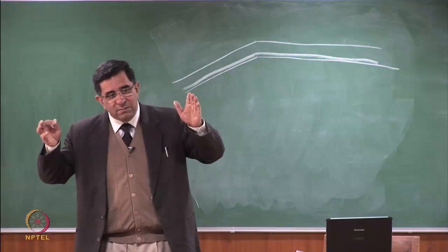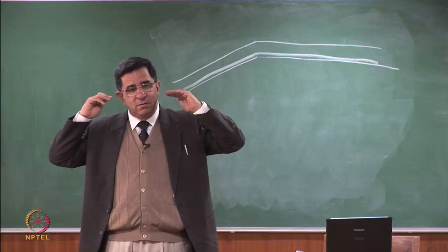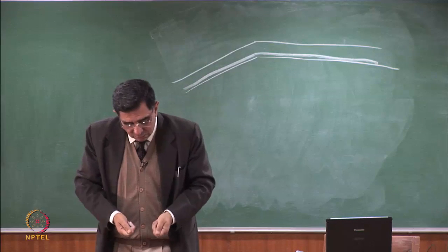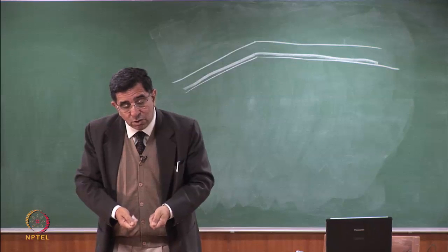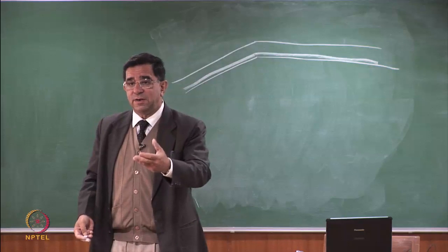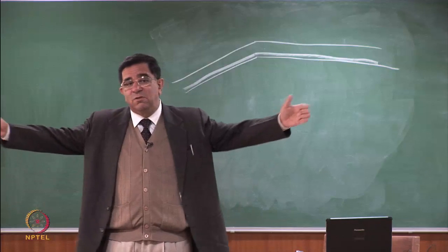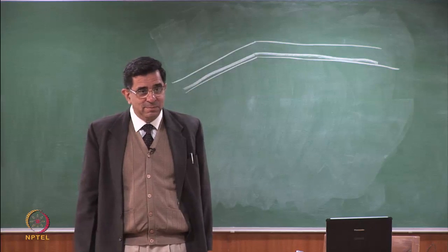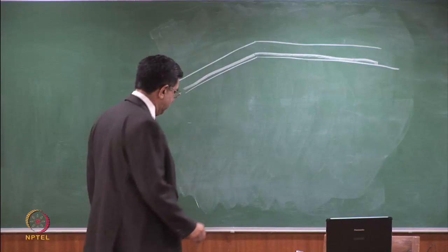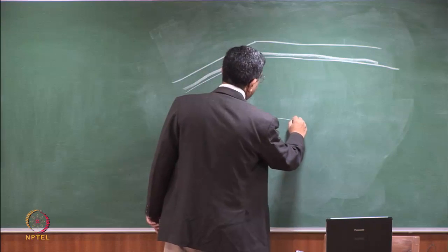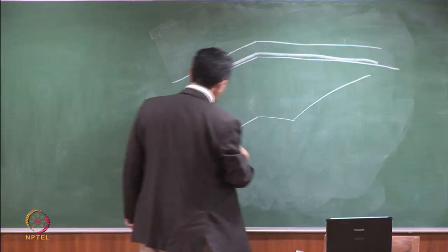At the top of a landfill, you may take a geomembrane very far horizontally, a few meters, to hold the geomembrane even if the soil wants to slip. Then the T will be generated. However, this long length may not be available to you. If you are on a berm, what will you do? This is your berm. Your geomembrane is coming.